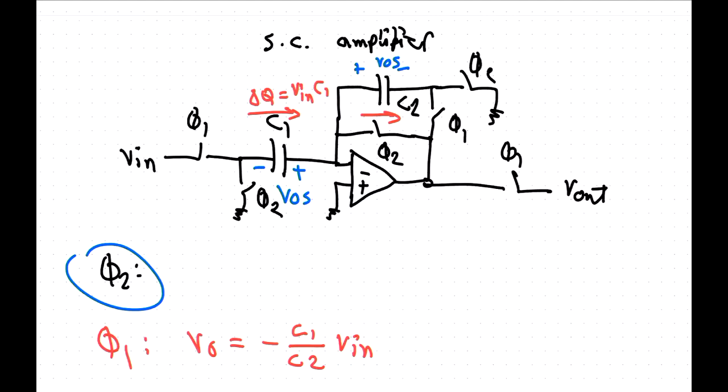But what you are using is digital LDOs and digital PLLs, where there are still bits in the analog domain. In an LDO, for instance, the output voltage is analog. But you wrap it around a digital comparator and close the loop in the digital domain, maybe with a DA converter sitting in there, or you can do switching. Essentially the control system becomes digital, and you just have a couple of analog components around it. The same thing with a digital PLL.